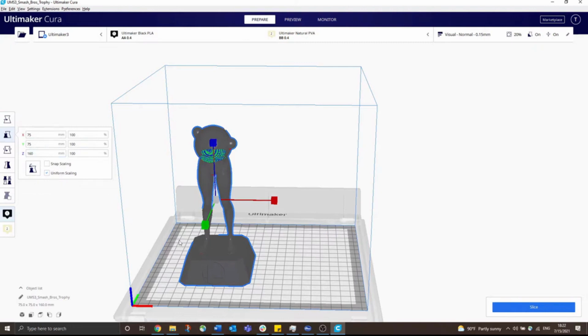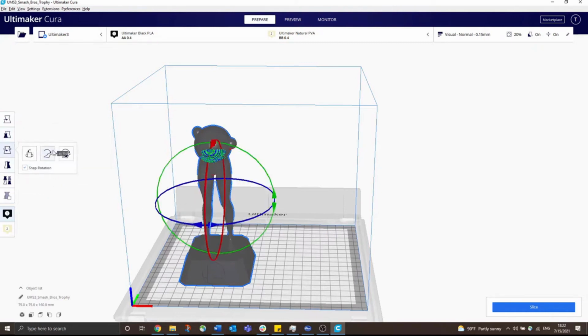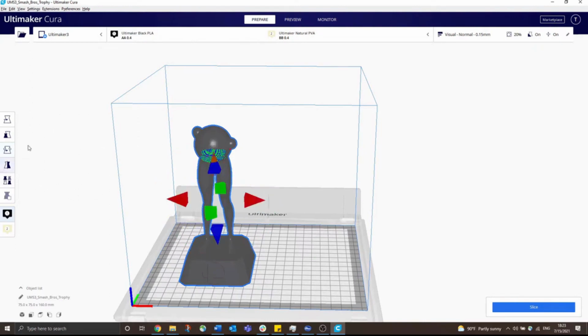You can do it by dimension or using the graphical interface. Same thing with rotate. There is a tool called select face to align to the build plate. All it is, you can choose your flattest surface or the surface that seems most stable, and you can print off of that surface. That just allows you to have a more stable print and to reduce your print errors.